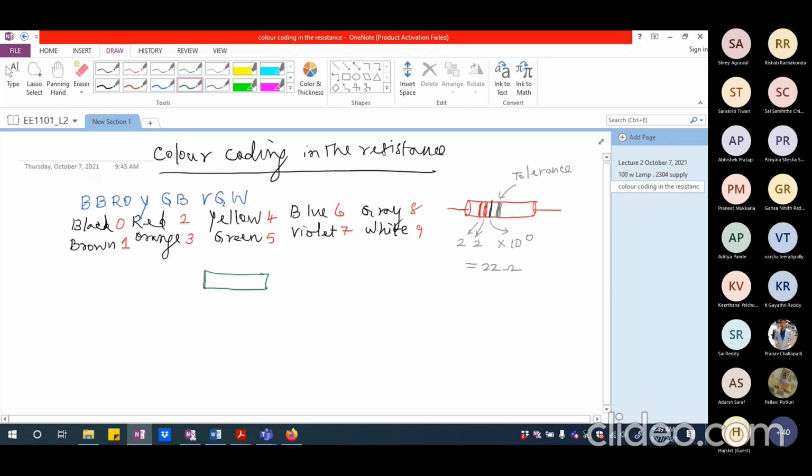So if I say that this is the resistance that I'm talking about, and these are the two terminals that are available. I don't know whether I'll be able to get violet, okay, let me get blue. So blue corresponds to 6. Please remember, blue corresponds to 6. And let us say I'm going to put a green color next. Okay, so this is green. And next, let me say there is a red. And after that, I'm going to have the tolerance ring.